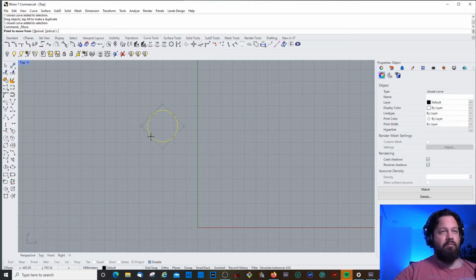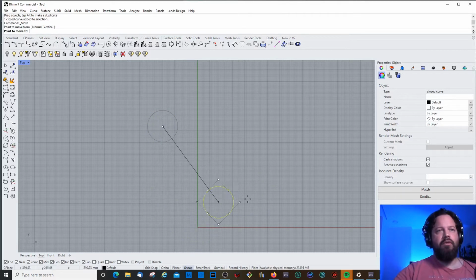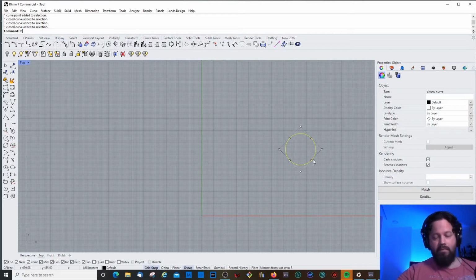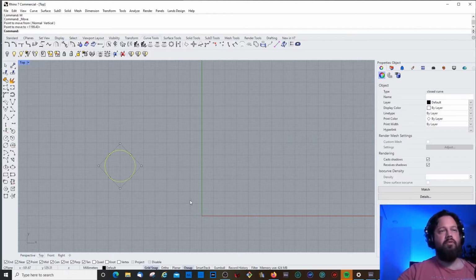And for example, let's turn the object snap on again. I want to place the circle center, so I snap the circle center. I want to place that to the origin of the plane. Then I just grab it. I could then move it around, could turn on my grid, or I just write the coordinates. M for move, and you move it.